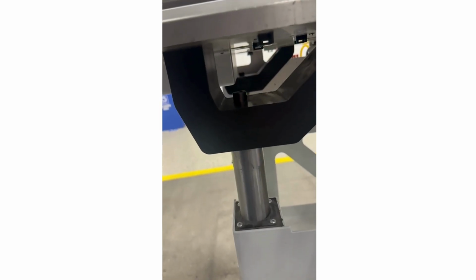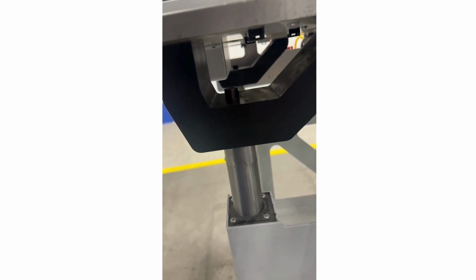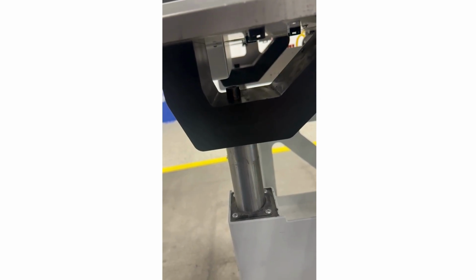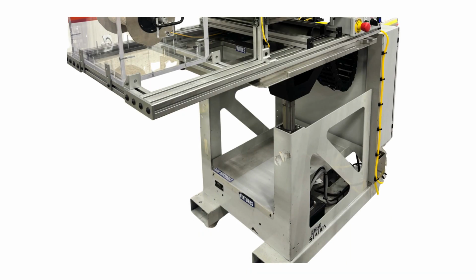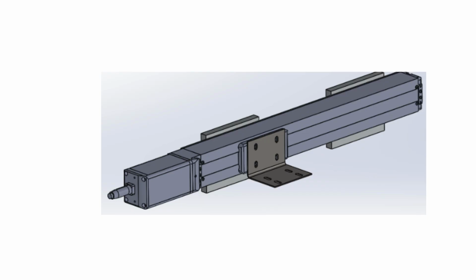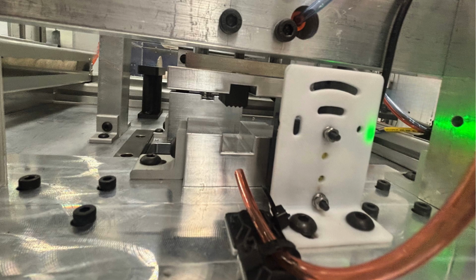The entire assembly is mounted on a height-adjustable ergo base that moves up and down for operator ergonomics and can be easily relocated using a pallet jack. Portability. Flat pneumatic grippers and a 45-degree guillotine eliminated fraying, slipping, and bending, and we exceeded our 85% yield target. For future improvements, the IAI linear servo can be downsized to reduce overall footprint, and the dispensing air blow-off can be optimized for cleaner thread ejection.